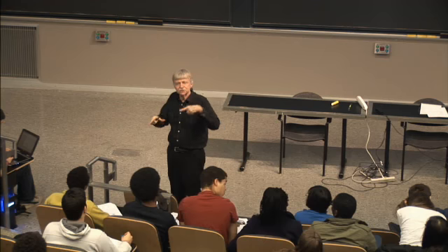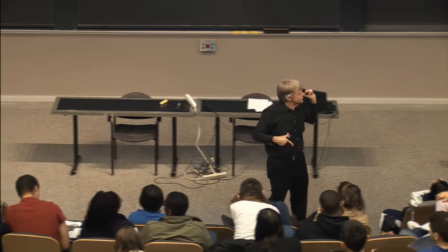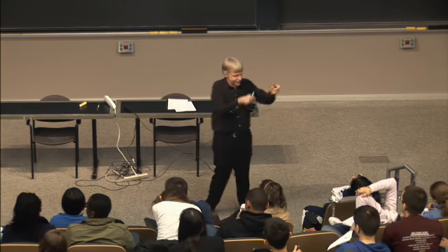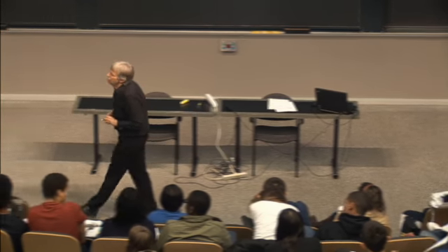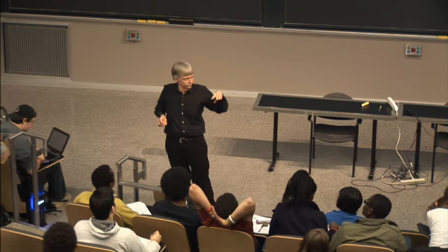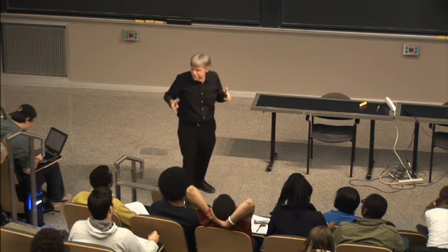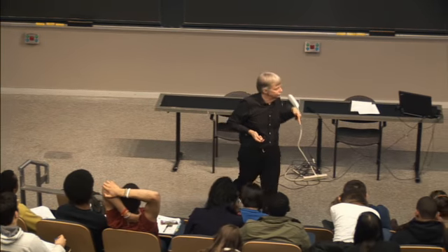So what I'd like to do is think about that for a moment. We want to be comfortable with the assumption that we make. The ideal op-amp assumption makes analysis really easy, but we'd like to understand exactly what we're assuming. This just doesn't sound right. OK, so let's back up. Let's not do the ideal op-amp assumption. Let's instead say that we use the voltage-controlled voltage source model.